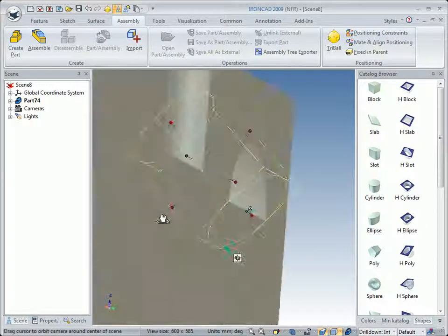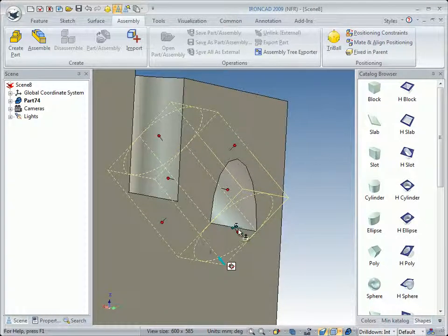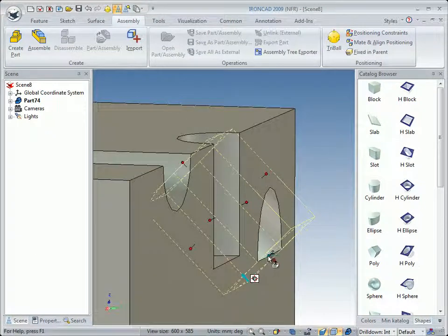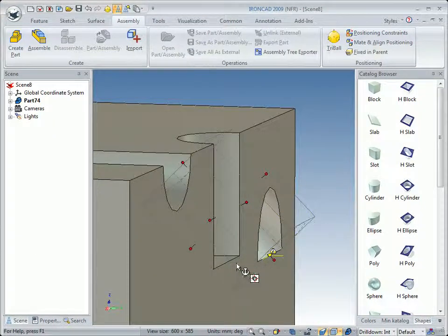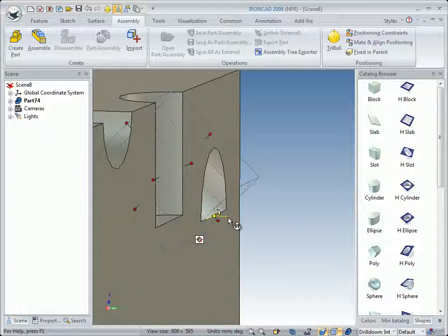And once again you see that it is the anchor that controls in what direction these shapes will be placed in the scene. So if I select this anchor, as you can see, the height axis is pointing perpendicular to this face, and the part, as the anchor controls, changes depending on where the anchor is located in relation to the IntelliShape.